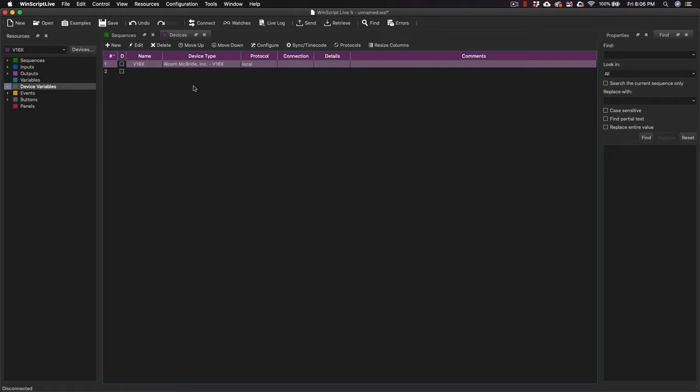Many of these configurations are unique to the device and product file used to support them. A product file is the description of everything that our controllers can currently do to communicate with a particular device. A simple one might just be a message instruction where you send your own message to a device. We have a generic implementation of this that is often used when needing to send TCP or UDP messages to a device that doesn't have its own product file yet.